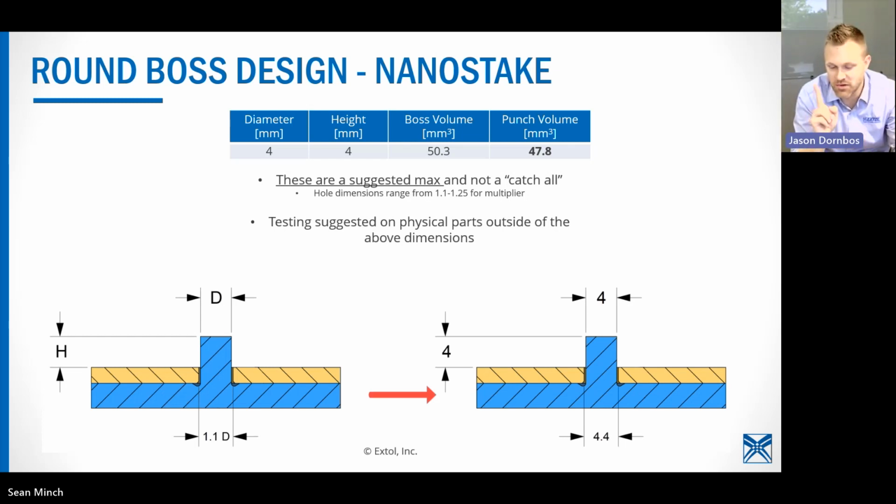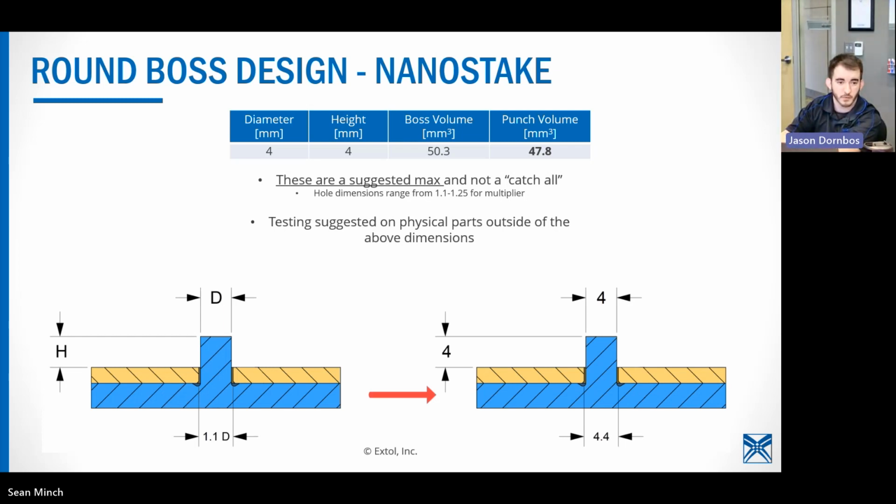So that's another scenario where sometimes tabs are used that I've seen. Yeah. And then just one more reason would be if you have a variation in your part location and you need to be able to compensate for left, like to one direction, you need to be able to have the mating component fit in a lot of different areas. If you do a tab, you can still get some decent retention because you're forming that tab over and clamping on the skinny side of your tab, and then you can leave the ends kind of open, and it allows for a lot more variation part to part. Some people even will choose a tab shape for concerns with heat sink with their mold.